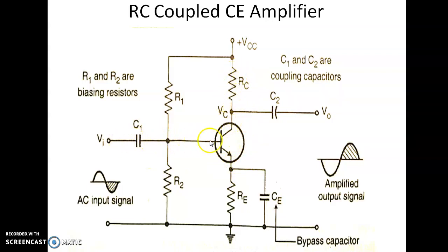As base current is constant, because we know that output impedance is very high, there is a large change in collector emitter voltage but a small change in collector current. Input impedance is low, so there is a small change in VBE, the base emitter voltage, but a large change in base current.